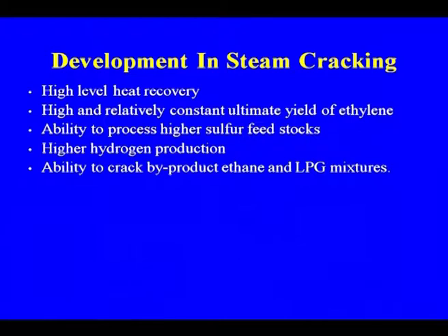So, high heat recovery and waste heat utilization are very important factors while going for a better design. High and relatively constant ultimate yield of ethylene, ability to process higher sulfur feedstock, higher hydrogen production, ability to crack byproduct ethane and LPG mixture.